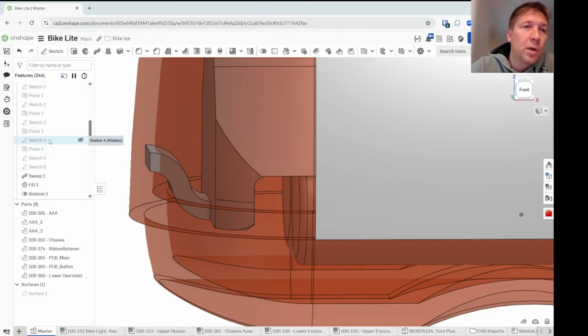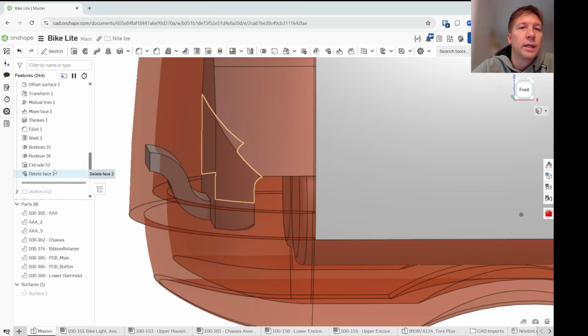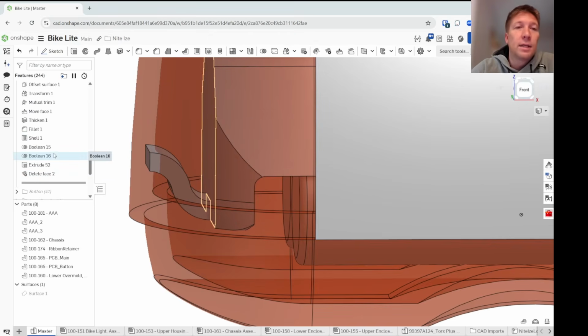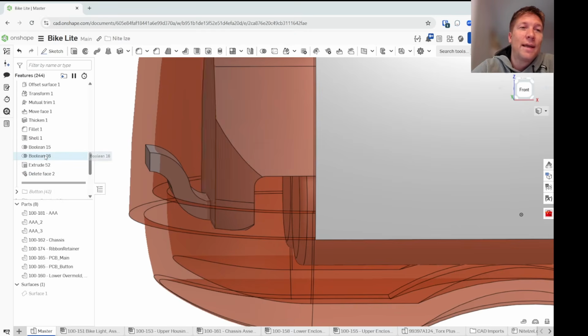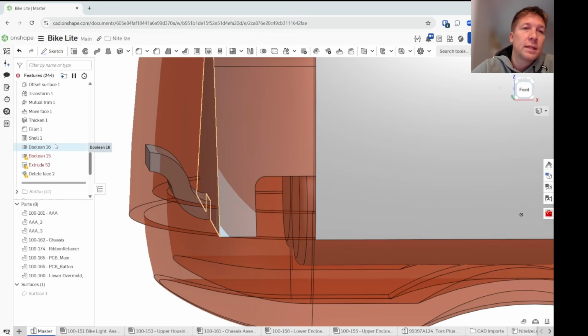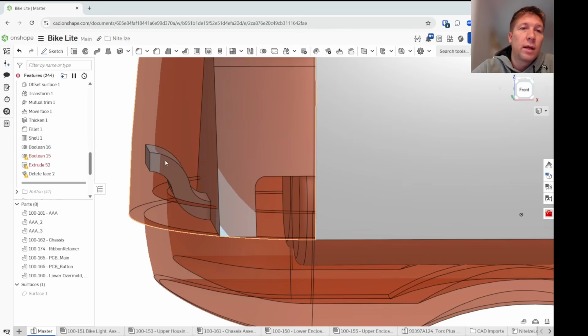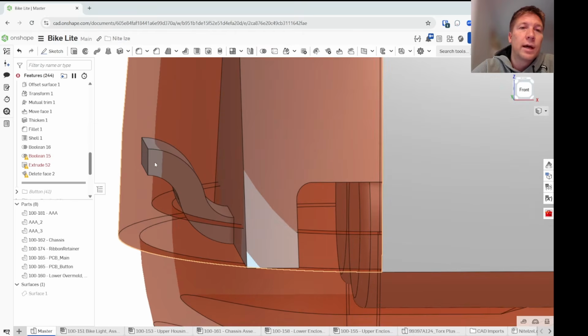So that part, actually, we could probably move that Boolean up in the tree. But just to explain, the reason I did this Boolean glue at this point and left these two off was because if I dragged this Boolean feature anywhere up in the tree before here, one, it might break, but two, the body is going to cut off the ends of these two S hooks.